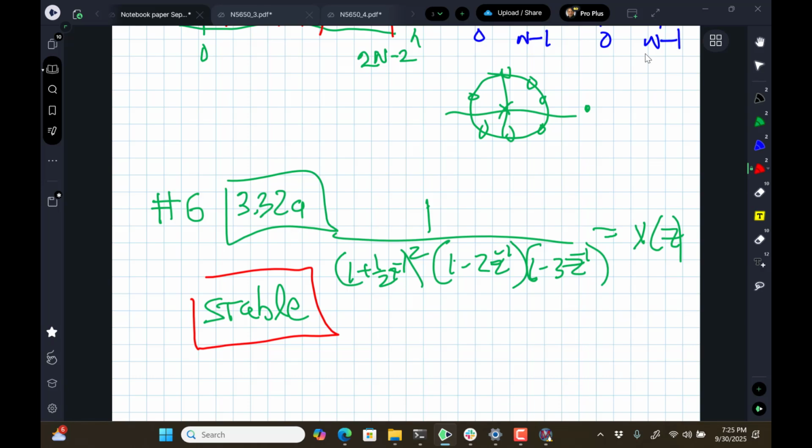The region of convergence has to include the unit circle. So the region of convergence is interior, exterior, or annular? It's going to be annular, right? Because if it's going to include the unit circle and you've got poles outside and poles inside, it has to be an annular shaped region. So make sure when you inversely transform, you get left and right sided sequence components in there. That must happen. And that will throw in minus signs because of the way the inverse transform pair works.